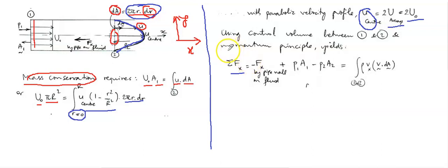So what sort of forces do we have along the x-axis? I previously said we have one force Fx, by pipe on plate, going in the opposite direction, so that's why it will be negative Fx by pipe on plate. We have the other force, pressure P1 A1 here, so we have force P1 on A1, going in the positive x direction, so this should be positive P1 A1.